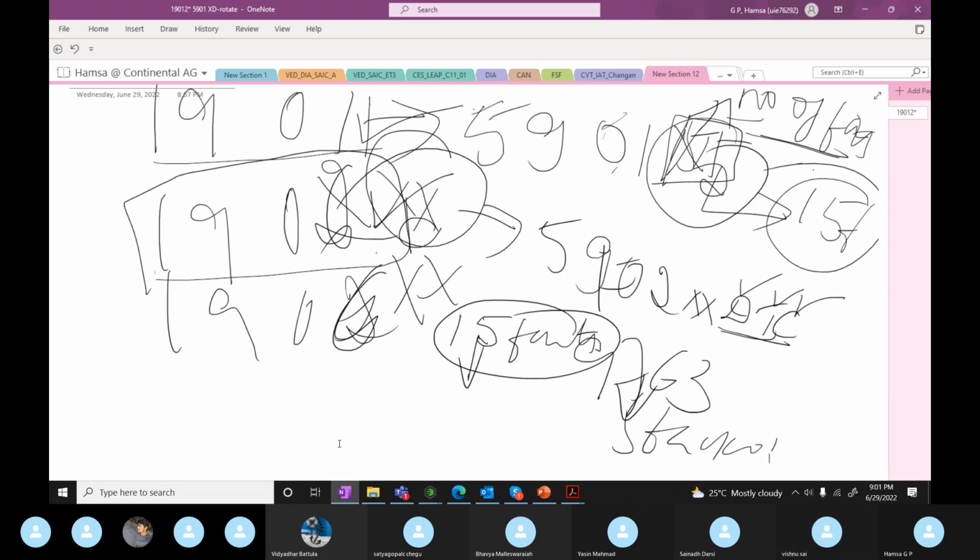So when it comes to 1906, in 1902, as we got to know, we will get the 15 DTCs, because there are 15 faults in the system. When you read 1901, you understood there are 15 faults in the system, but you don't know what those 15 faults are. That is the reason you requested 1902, where you will get the DTCs, which are the faults set in the system. So 15 faults are set in the system. How would you get to know what they are? With the DTC, diagnostic trouble code. Clear?